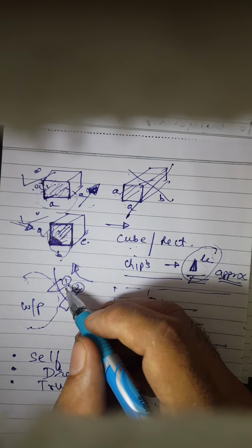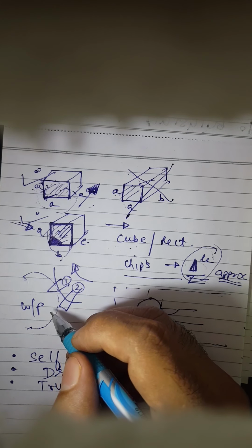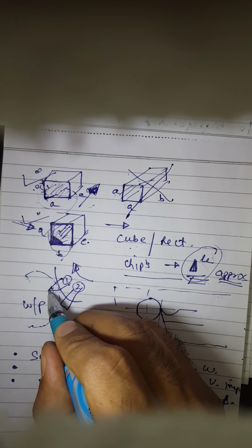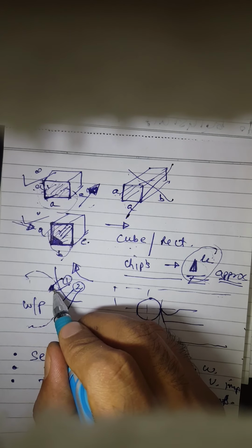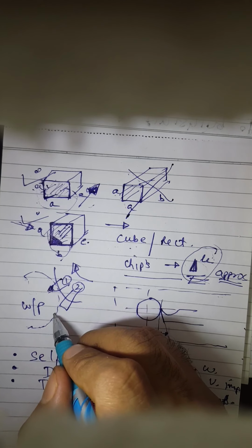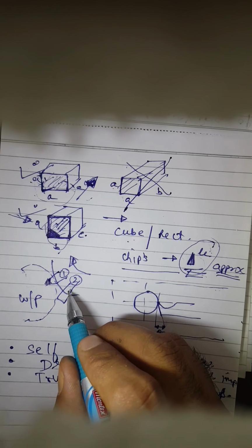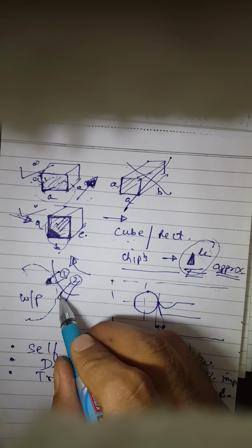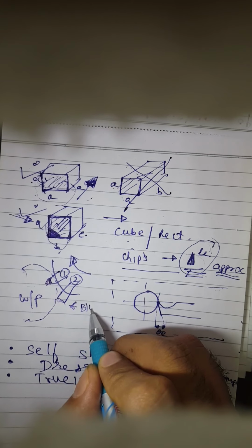So over a period of time, particle 1 is always going to come into contact with a fresh workpiece surface, which means that as this edge is exposed to the workpiece surface, there may be wearing of the abrasive particles also, and this edge may get blunted over a period of time. And so when it gets blunted, ultimately it may assume a shape similar to this. I'm not saying exactly like this, but similar to this, which I may also call a blunt shape.